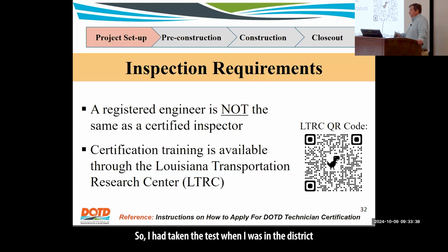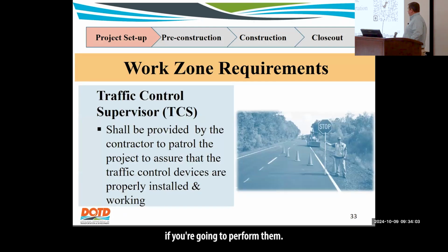So I had taken the test when I was in the district to make sure that when I'm making a concrete cylinder, the contractor doesn't come back and say those weren't created correctly, because they had a low break, and we're going to end up throwing that out because I, as the project engineer, made it. Make sure that you are certified to do those things if you're going to perform them.